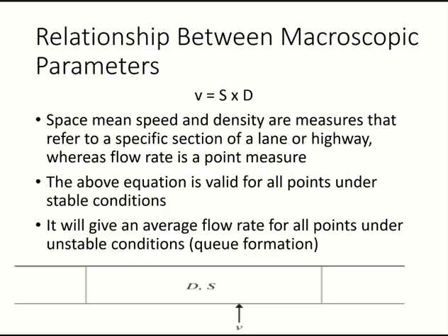Today we will start with this equation, which is the main equation of traffic flow. Now keep one thing in mind. Whenever I say this equation applies to traffic flow and that equation has speed in it, it is always space mean speed. Any equation of traffic flow, when it has speed in it, it is space mean speed. What is the other mean speed? Time mean speed. Good.